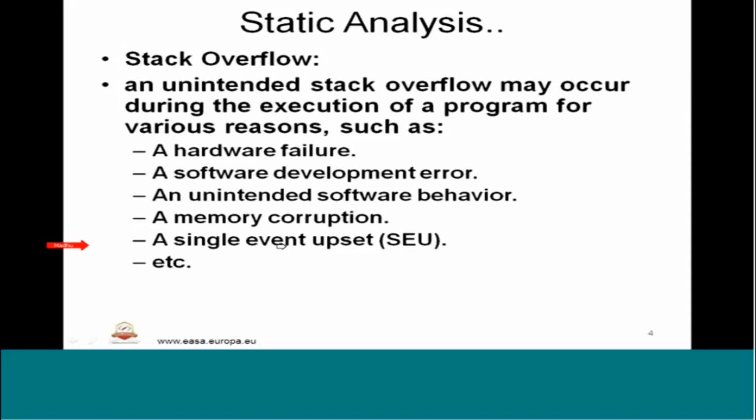Typically they take the approach of filling the memory with a certain memory pattern and executing a test which forces the maximum usage of the stack. So here is the stack and it is filled with a known pattern, such as A in the first line and F filled in the next line.